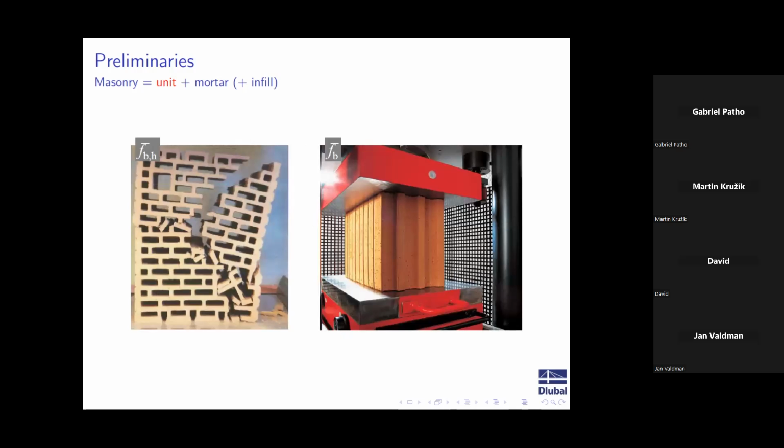And you can do some tests. These are photographs of actual masonry unit tests. You have some compression tests in both directions. Let's call here on your right picture the strong axis, because this is the better direction, what they usually want to load. And the perpendicular one is the weak axis because of the holes in it. This one fails much sooner than in the strong axis.